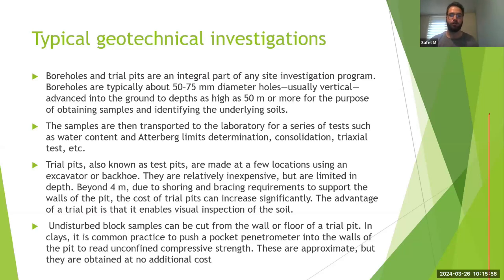Trial pits, also known as test pits, are a lot cheaper option. With trial pits, you're looking to get around 4 meters maximum, depending on your excavator and your type of excavating. The advantage of the trial pit is that it enables you to do a visual inspection of the soil. You can do the same thing in a borehole, depending on the type of boring that you use.